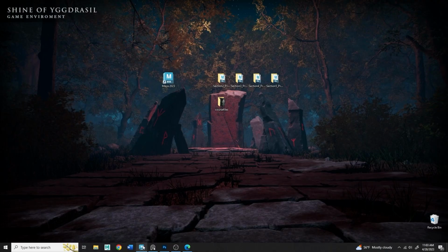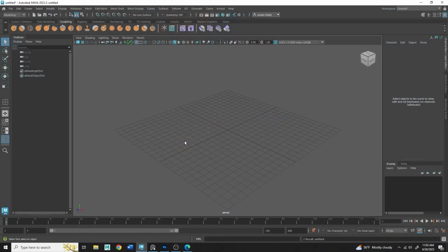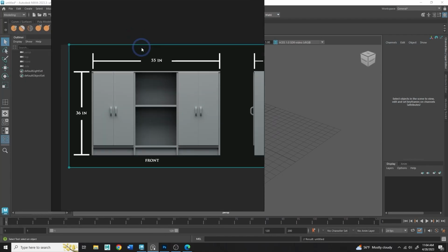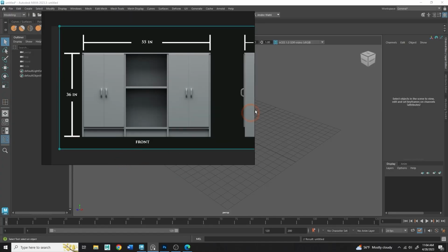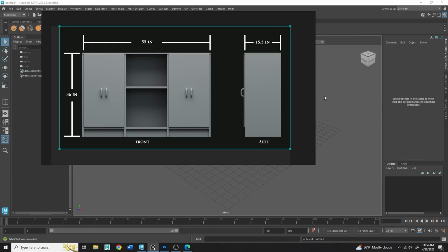Now, coming into Maya, we can set up our file so we're ready to work in the proper units. If we take a look at this, you'll see that it is currently working in inches, and the default unit inside of Maya is in centimeters. So we're going to want to switch over to this. It's important that we work in real-world units inside of 3D to ensure everything fits together in the end. And I believe we may have discussed this in a previous section, but now that we're creating a larger production that's going to have multiple working elements that all need to look correct in the scene, we're really going to want to pay attention to this.